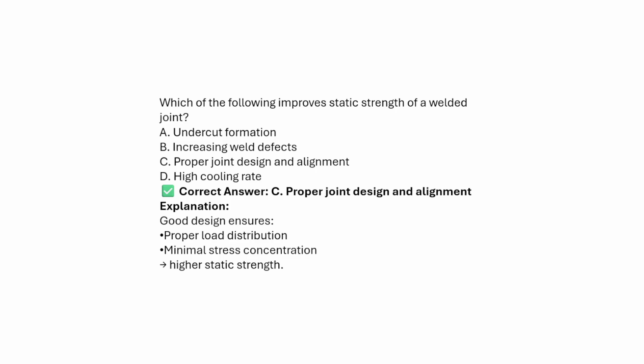So the answer will be proper joint design and alignment. Good design ensures the proper load distribution, minimizes the stress concentration, and that results in the higher static strength.